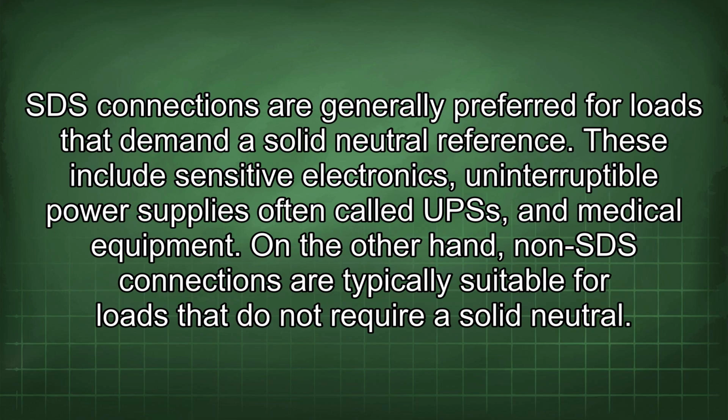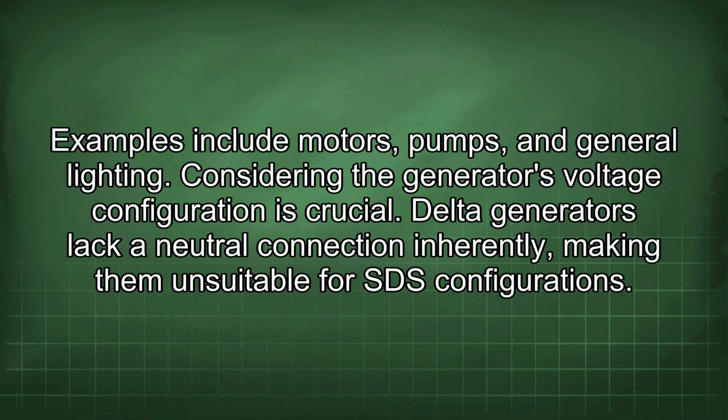SDS connections are generally preferred for loads that demand a solid neutral reference. These include sensitive electronics, uninterruptible power supplies, often called UPS, and medical equipment. On the other hand, non-SDS connections are typically suitable for loads that do not require a solid neutral. Examples include motors, pumps, and general lighting.